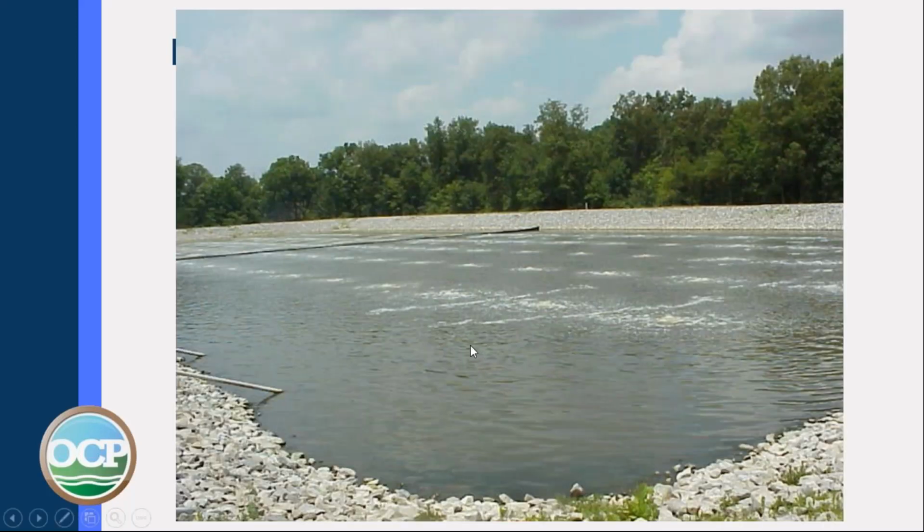If you take care of your lagoon and follow the right O&M, do everything the way you're supposed to, you'll get a fine looking lagoon like this one. You can see the aeration. This uses underwater aerators. A little bit of light froth on top that breaks quickly. Doesn't appear to be any dead areas except maybe over here in the corner. Looks real good. They've got a curtain to keep the flow from running straight through.